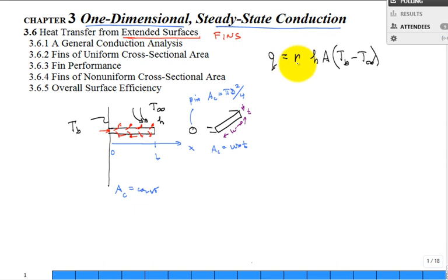Well, we make a modification, we put a Greek letter right there. Oh, I forgot the name of that Greek letter. Theta? Eta, that's right. And we put eta subscript f. That's going to be the efficiency of that fin. If the fin is made of super high conducting material, basically the base, the tip, and everywhere along that fin have the same temperature, the base temperature, and eta would be 100%. But real fins maybe have efficiency of 90% or 80% or something, okay?